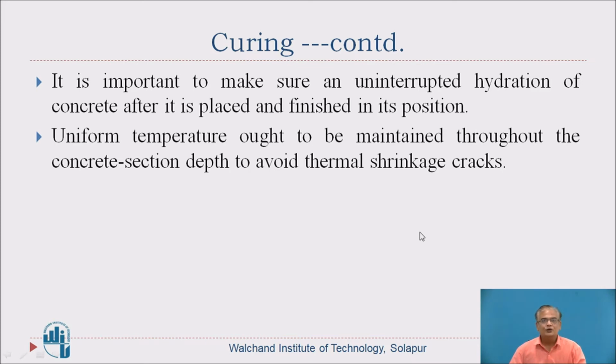Uniform temperature ought to be maintained throughout the concrete section depth to avoid thermal shrinkage cracks. Remember, friends, temperature of the concrete component should be kept uniform. Otherwise, what will happen? Thermal cracks, shrinkage cracks will appear, and those will open under the effect of external loading, and concrete will not be a durable one.